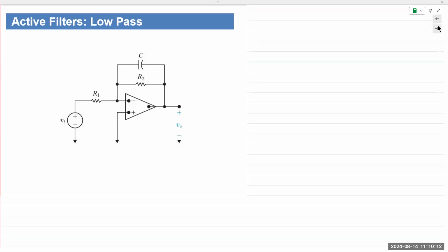Capacitors and inductors are energy storage devices. They receive the energy from the source, from the circuit, and then they release it back into the circuit at a later point in time. So there is an energy transfer that takes place constantly between the capacitor and the inductor and the circuit. Now, this energy transfer cannot take place instantaneously. It takes a finite amount of time for the energy to be transferred back and forth. This period is known as the transient period.